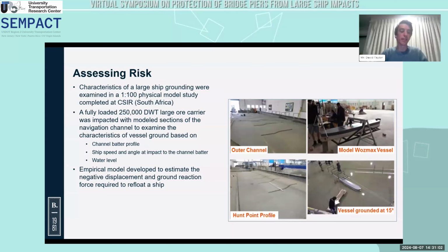But the key risk area is if a ship is transiting near high water, that ship can remain grounded for many hours or even days to weeks, depending on which part of the tide cycle. If it's falling into a neap tide cycle, it may be up to 20 to 28 days later that a similar tide level might be achieved to the tide level at the time